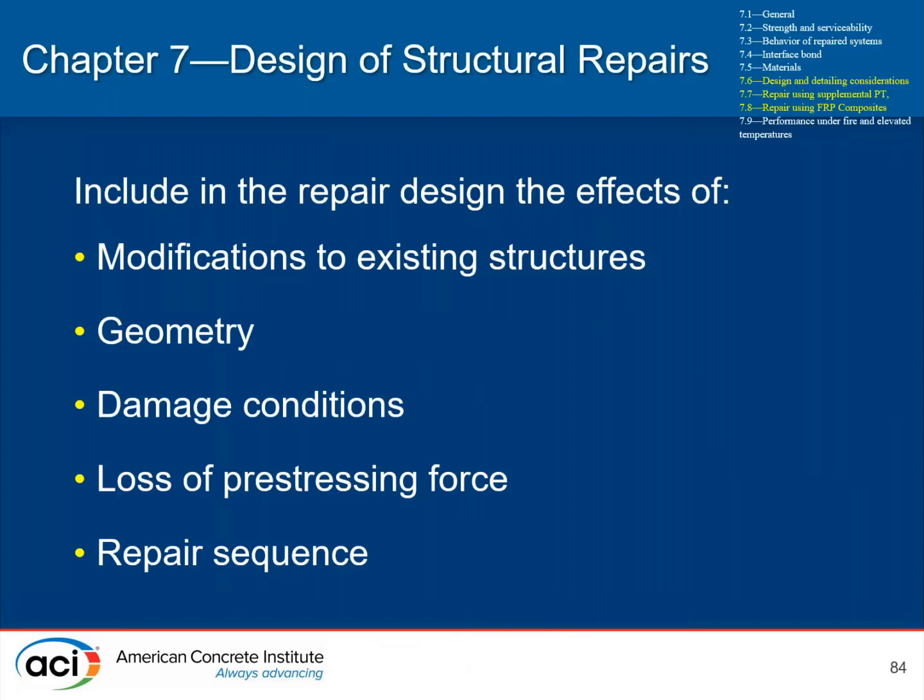So the design of structural repairs and detailing considerations is going to include the effects of the modifications to the existing structures, the geometry, damage conditions, any loss of pre-stressing force, and also the repair sequence. That can become very important when you're removing or repairing large sections of the structure, but it certainly should be considered as part of all repair methodologies.